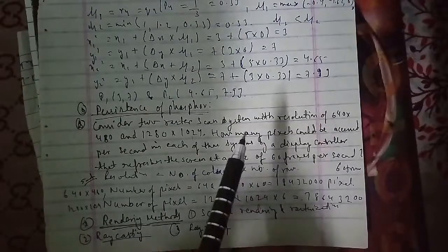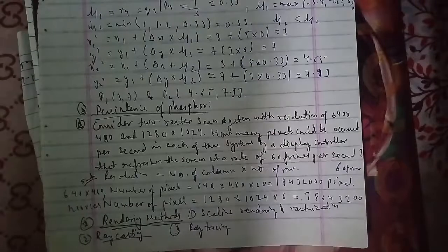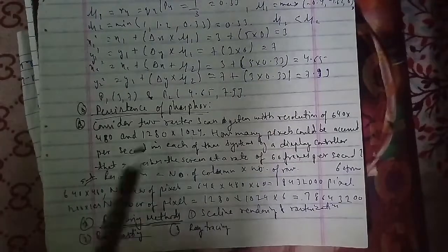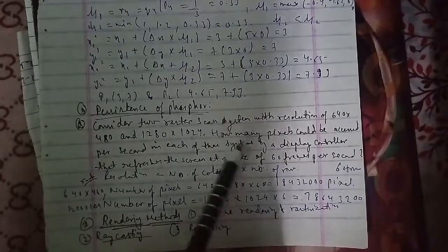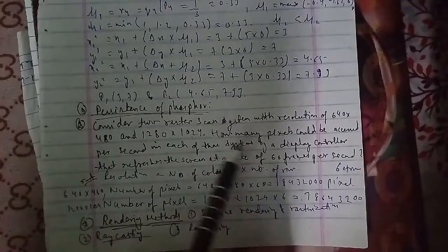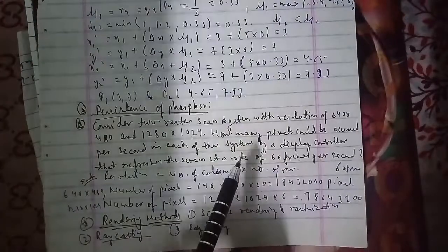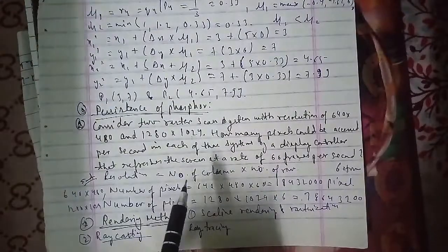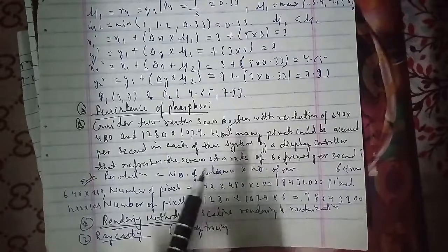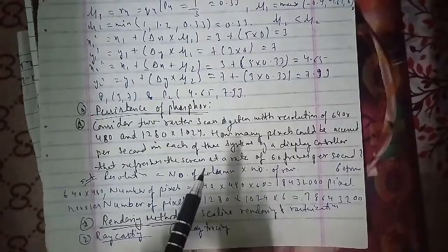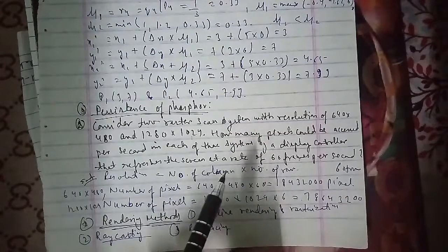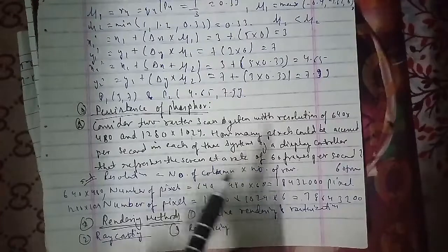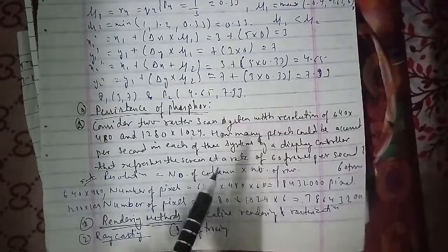The second is that the curve resulting from the use of the open uniform is based on nearly like Bezier's curve. The curve generally follows the shape of the defining polygon in Bezier, and in spline the curve follows the general shape as well. The third difference: these curves can be used to construct the blending curve. Bezier curves are commonly found in painting and drawing packages as well as CAD systems. In spline, the typical CAD applications include the design of automobile bodies, aircraft and spacecraft surfaces, and ship hulls as well.